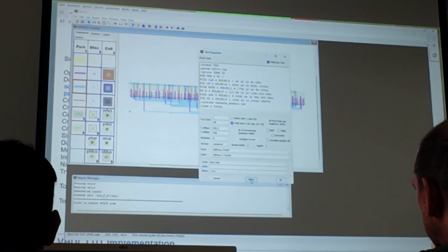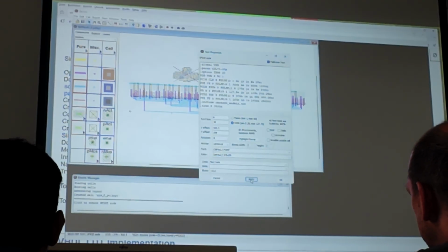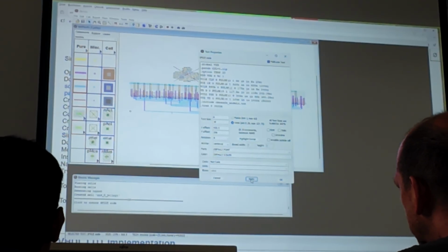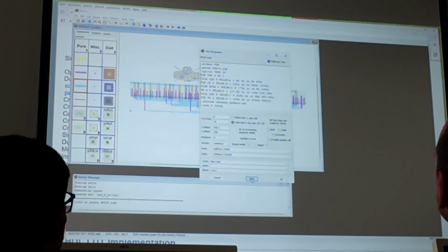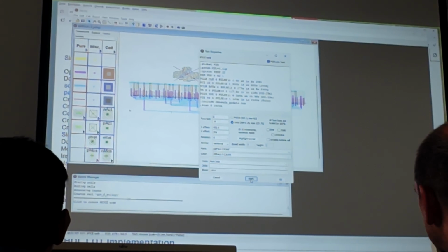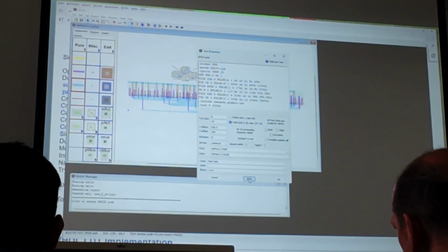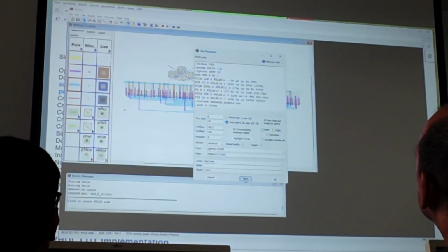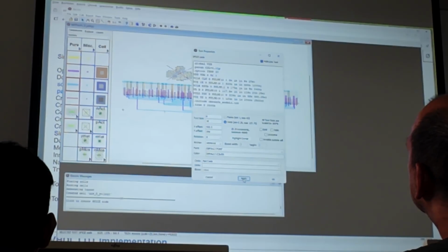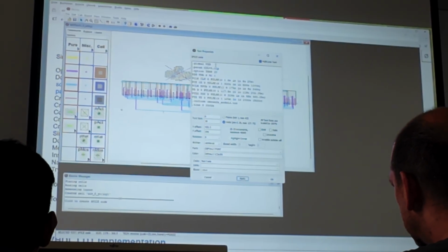How did you get to the text properties? As soon as I make the SPICE code, there is a very small X. As long as this X is still selected, I can go to the edit properties. Okay. And then I get something here.